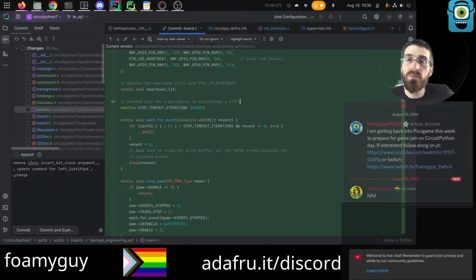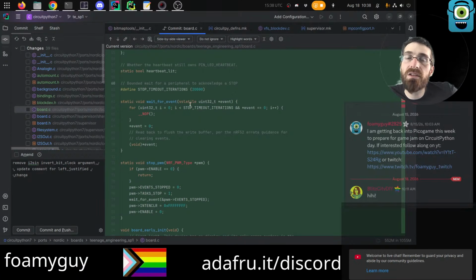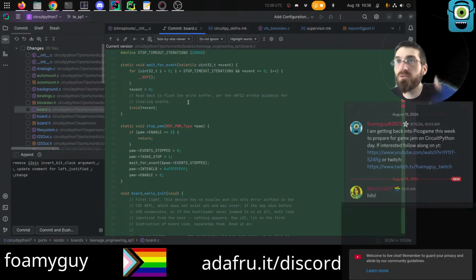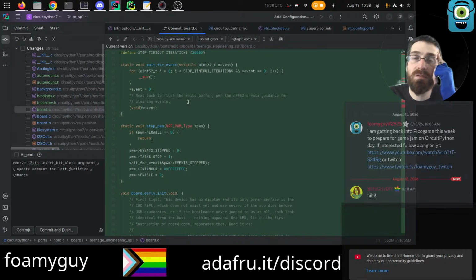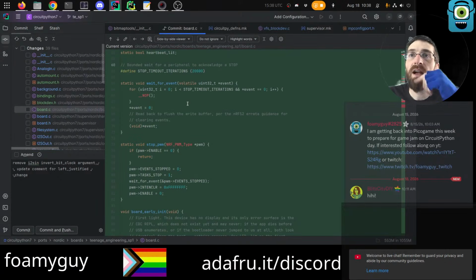And again, maybe it's actually 5 or 6 seconds, but I did 4 to be safe. And if we don't, then the device will reset. So basically any spot where there's something that is doing whatever for more than 4 seconds, it had to have a bit inserted that's like, if the watchdog is enabled, then feed it.